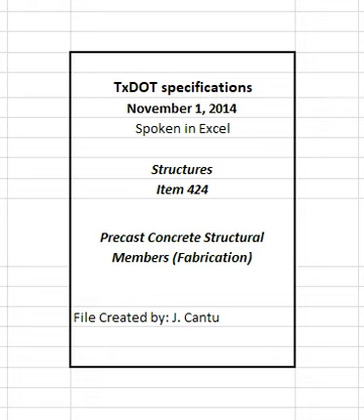Heat the strands over an approved strand length and duration when flame detentioning so that the metal slowly elongates and gradually loses strength. Do not abruptly flame cut strand by holding the heat source in a concentrated location on the strand. Submit the flame release procedures and sequences for approval. Approval of flame release sequences does not relieve the contractor from responsibility for meeting the product workmanship requirements of Section 424.4.3, Workmanship. Release the tension in the strand.